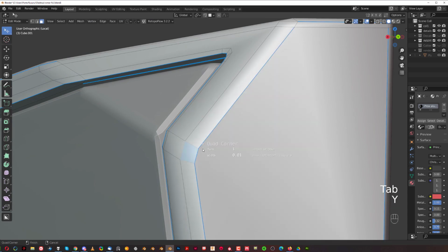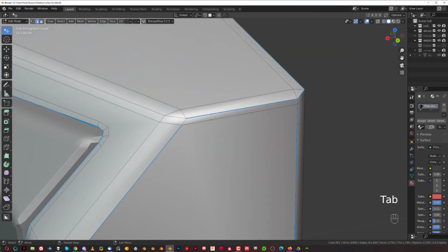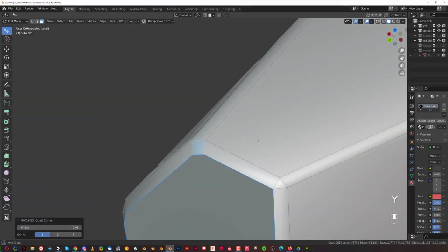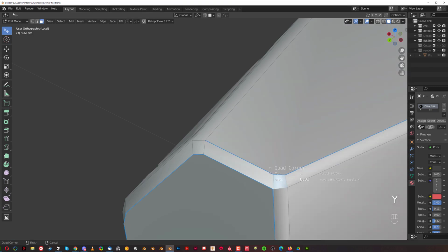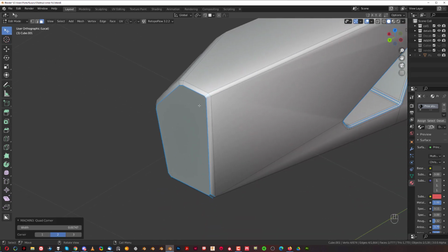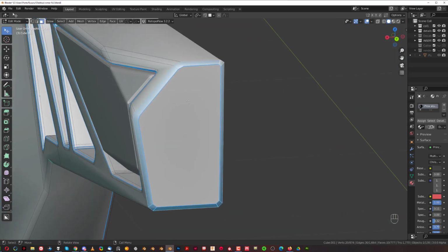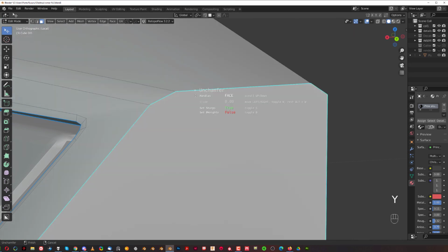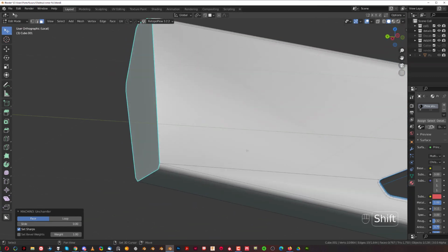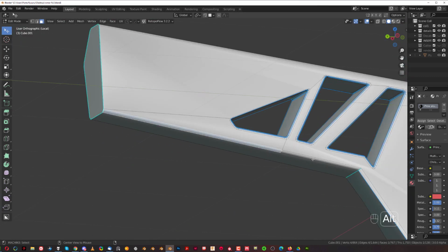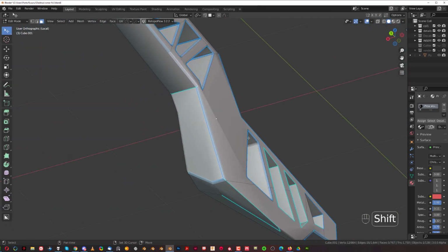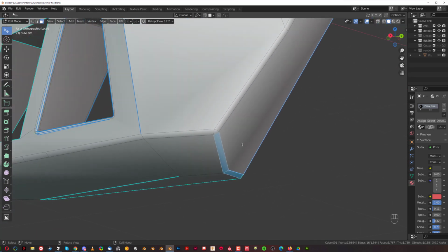Select this one and quad corner. And then go to the top, remove this edge, and quad corner this one, and quad corner this one, right? And remove it. So the flow is around this edge, see, like this, right? Because this corner is gonna determine where the flow goes, right? And unchamfer. So we got this unchamfered in the front, perfect. And let's see this one, how we look in here. So let's just select this. Let's see where it flows. It flows all the way around and it ends here, which is okay.